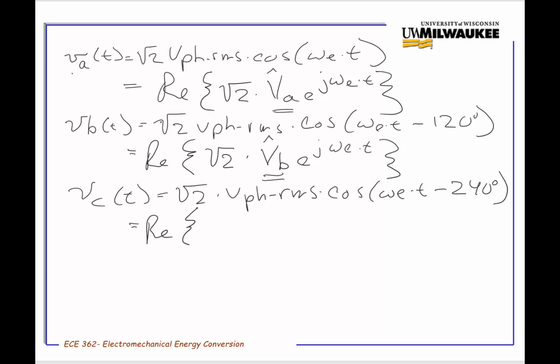The mathematical representation of the time variant phasor is the square root of 2 times a stationary complex phasor VC, times the rotating part here. Okay, so now I've actually gone into this aspect of phasors and scalars in a little more detail than maybe is needed, but hopefully some of you will appreciate the insights.